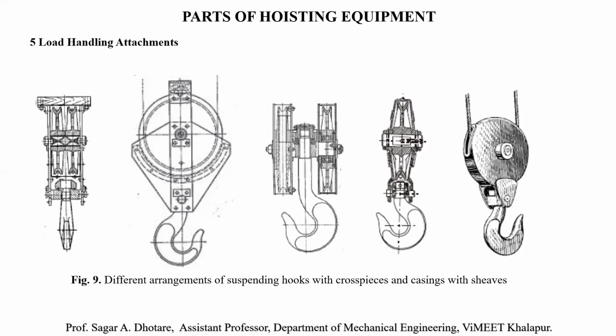The body of the hook is generally trapezoidal in cross section, ending at the top in a round section working under tension. The top part of the shank is threaded for suspension from the crosspiece. Hooks are mandatorily to be tested under tension load and certified before use.